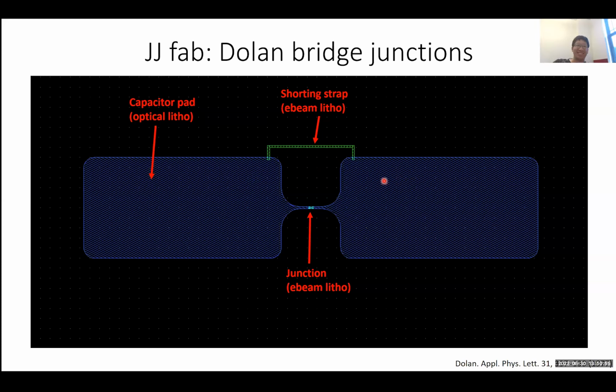One thing I also want to say is that from our experience and our measurements, we haven't found any degradation of coherence by adding the shorting strap. We don't see any penalty in terms of additional losses, so we just opt to put it in. But you have to scrap them later on, right? Yes. Before you cool down your device, or when you want to probe your device, you do need to break this. That's right. Okay, thanks.